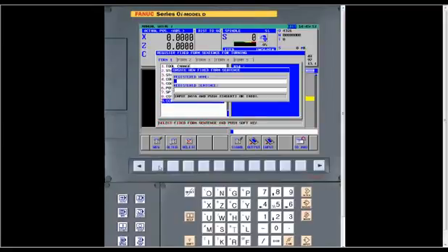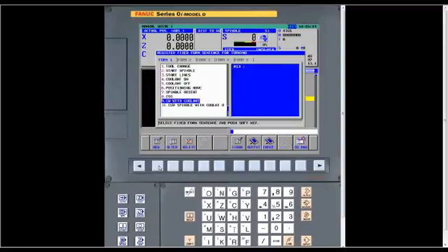So what we're going to do, we're going to make a new one. If you press new, it comes up with this. And the first thing it wants is the name of whatever fixed form that you're selecting. And we're going to say clockwise with coolant. Press enter for input. And then it says registered sentence. And I know that's M13, end of block, insert. See, it puts it into that. Wherever the cursor is, that's where it is. So we made a new one there.